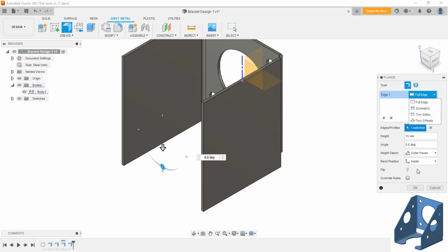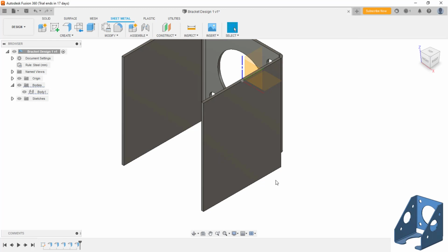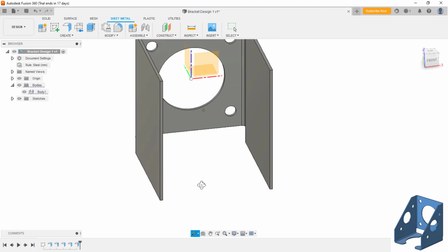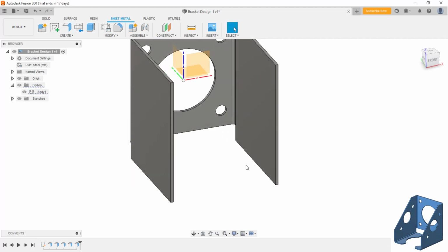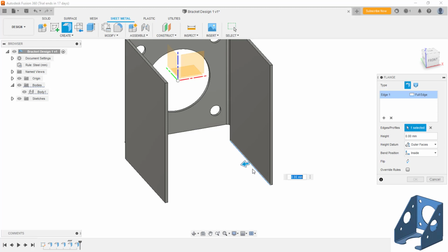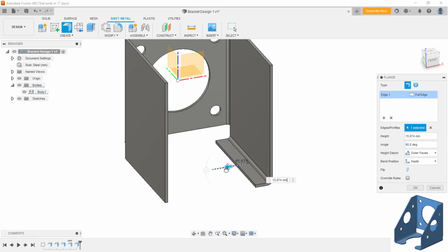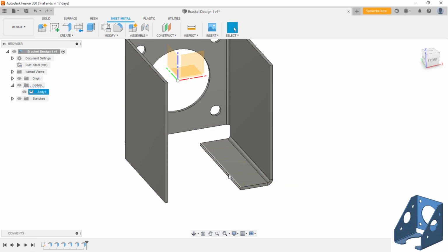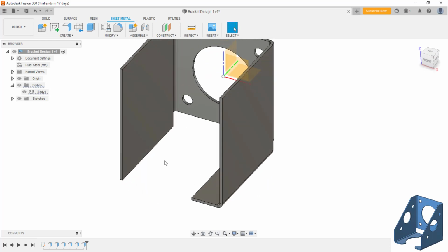So these are the different options while extending the material. If you want to extend up to a certain length, you can even do it. Yep, so now I'll again use the same edge flange feature. I'll try to extend this edge. You can see the completed model at your right corner. So I need these extended edges. I'll take the length as 30. So same thing this side.